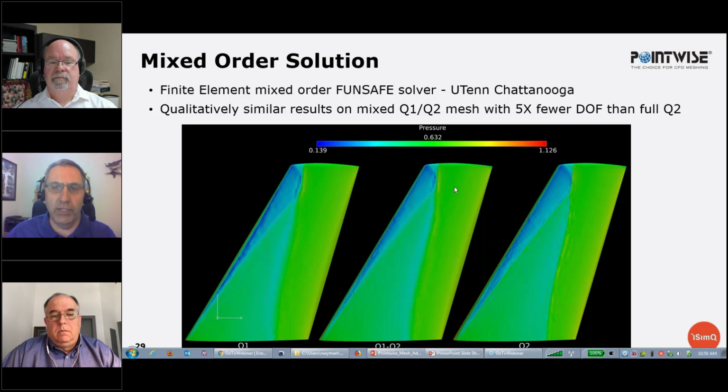So we always start with a coarse but best practice mesh. It's not going to be 5,000 cells. It's going to be a larger mesh that is resolving the geometry to best practices, that is building a boundary layer mesh that the chosen turbulence model is expecting. This mitigates it.